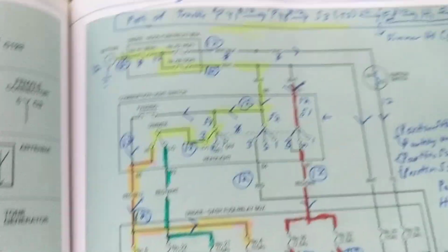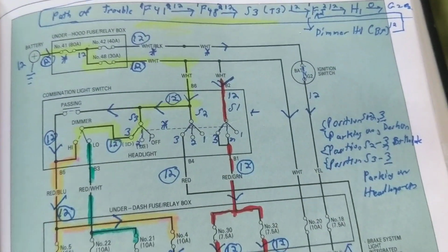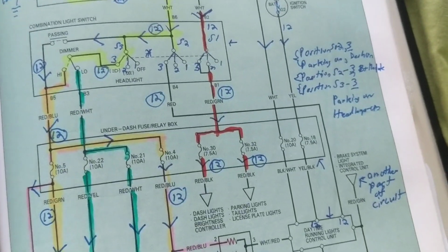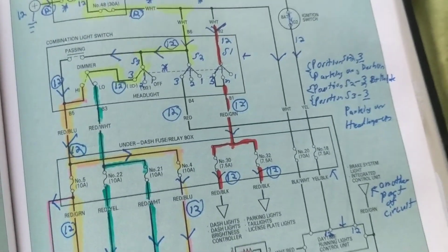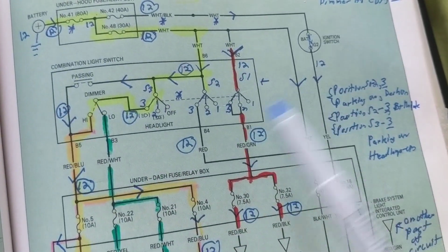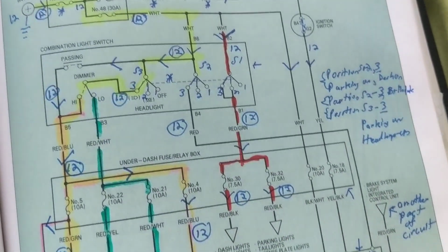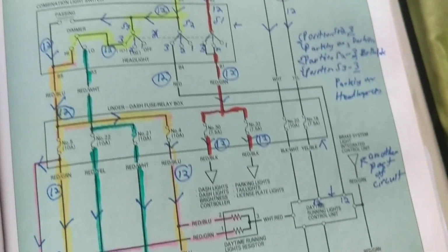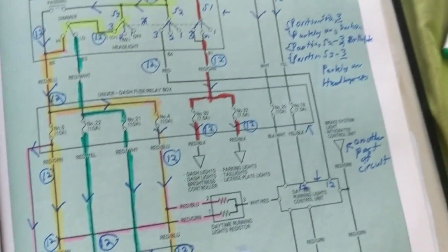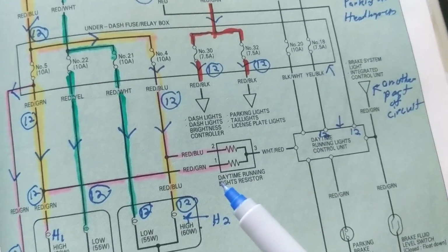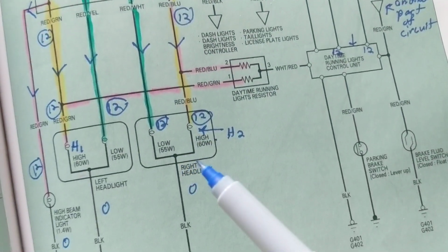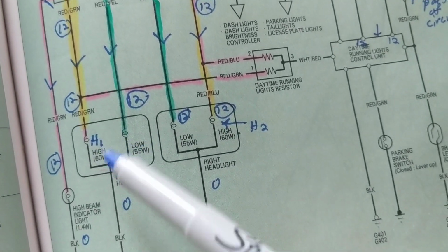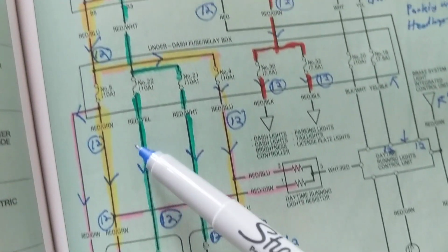Now let's start at the schematic. Where do you start first? And this is a question that I always focus on because it's a little confusing to the viewers. We're going to delve into how to understand a schematic. So we can start from here. The basics. If you're troubleshooting, which we'll do later on, we're going to focus on main components. So if there's a headlight problem, I'm going to go to the headlights, look over here for the headlamps, and work my way back up.